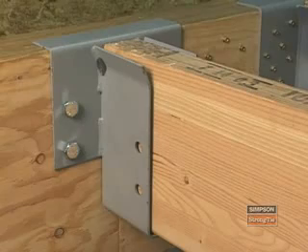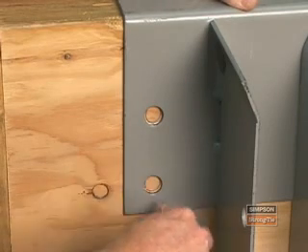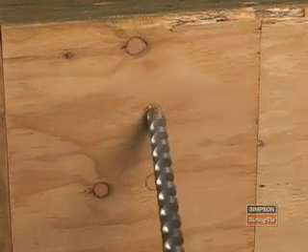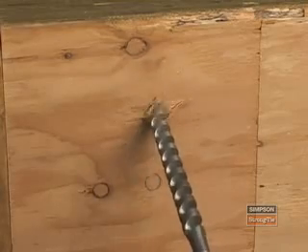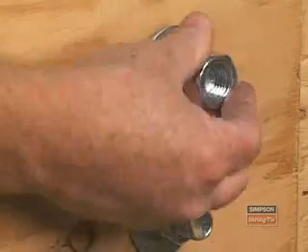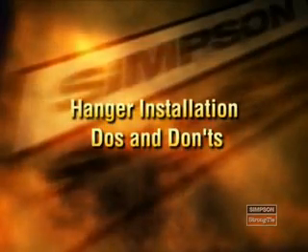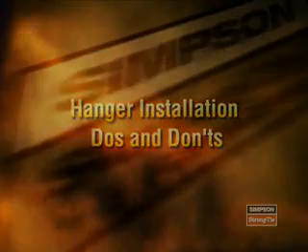Some beam hangers require bolts. Before installing a bolt, you must first mark the bolt location, then drill a hole with the correct diameter all the way through the carrying and carried member. Be sure to use a washer on the wood side of the bolted connection. Following is a list of basic installation do's and don'ts that help you ensure that you install the hangers correctly.